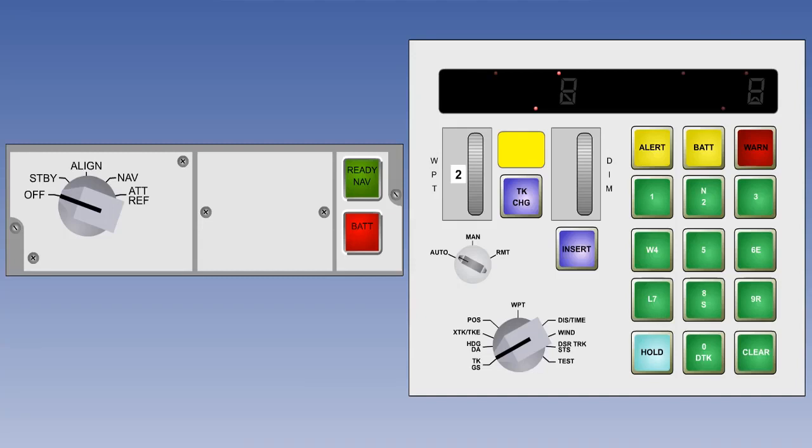This lesson describes the operation of typical 70s-era inertial navigation systems such as the Litton LTN51 and the Delco Carousel. Before any INS operation can take place, both AC and DC power supplies must be available from the aircraft bus bars. These may be initially provided from an external power unit or the APU. Eventually, the power must be provided by internal aircraft power from the alternators or generators.